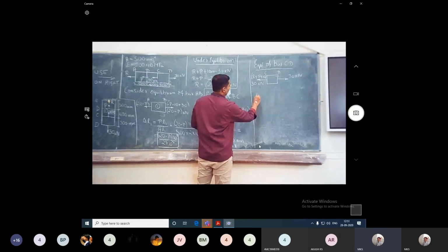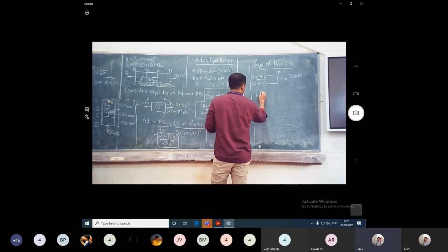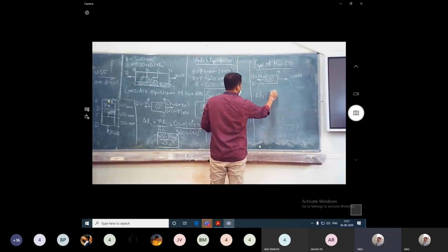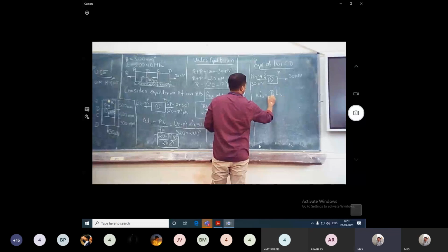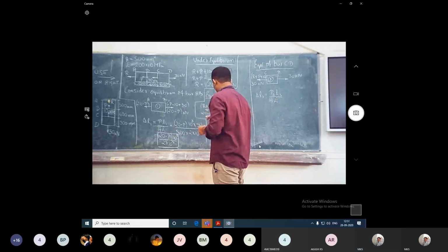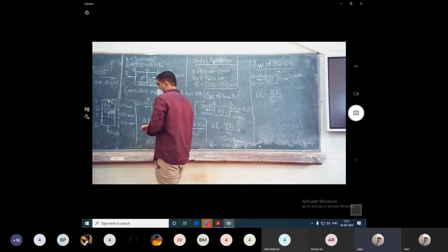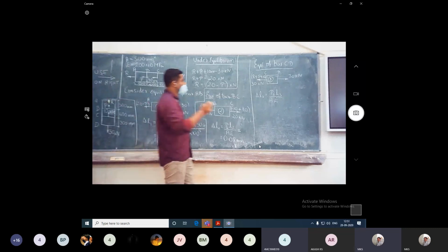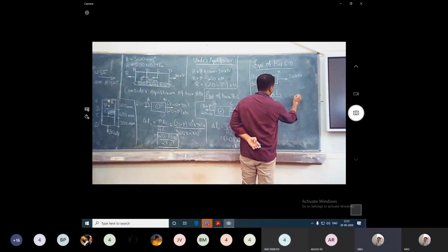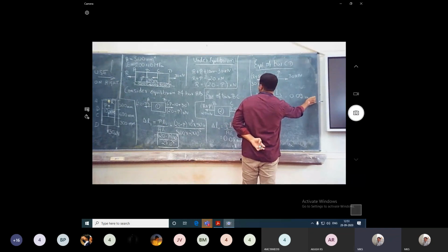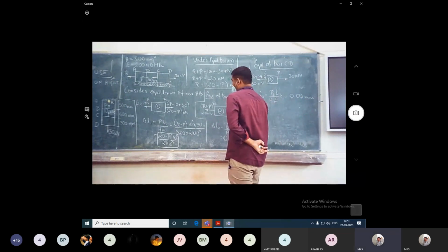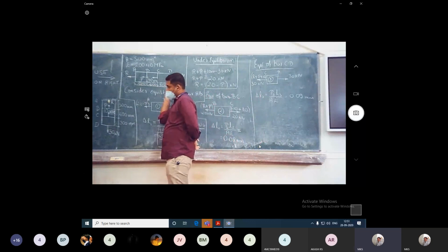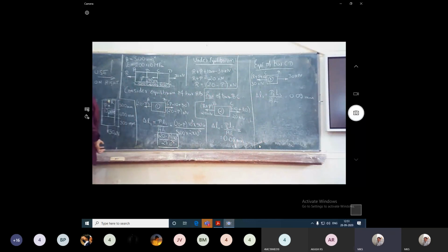So now you find delta L3. We'll consider this as section 3. So delta L3 is equal to P3 L3 by AE. How much? It is 0.09 mm. Now you find the total elongation of the bar or total deformation.